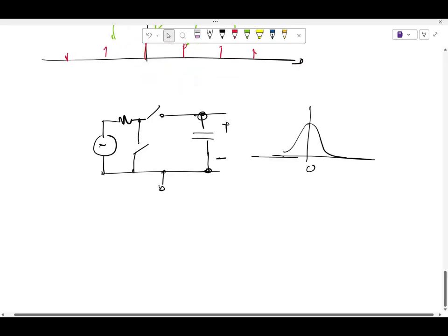Okay, so now I'll take the next step. This part is similar to what we did in that day's lecture. Once we have the voltage across this capacitor, I want to find out the voltage at this node on the other side, right? So this should be very simple. What should I do? Multiply with S of t, right? Which means convolving with the impulses of the transform of S of t, right?